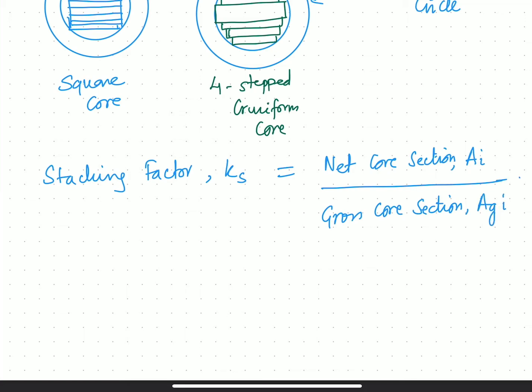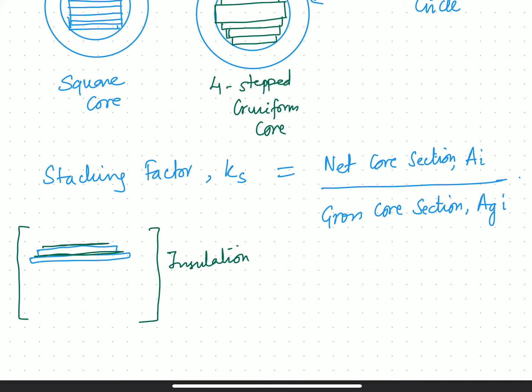So why is this different? Because like I said earlier, you have these laminations, and on this lamination you apply a thin coat of varnish, right? Then you have the next layer, then you have another coat of varnish. So the total area, the assembly, also has a portion of insulation in it. This green varnish is actually the insulation.